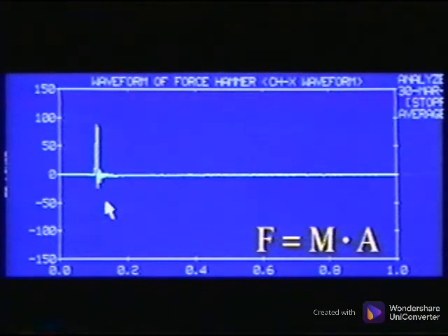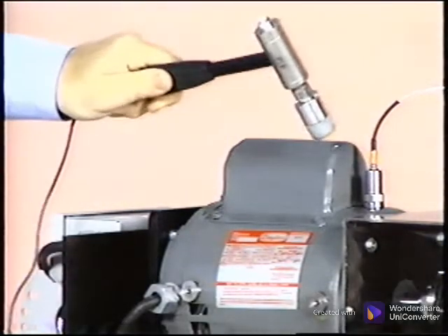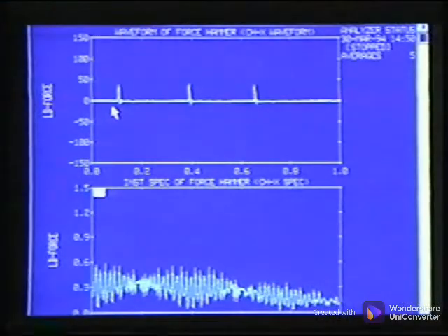Again, the waveform data has the most useful information. In acceleration, these impacts are proportional to the force. When 2 or more impacts occur, the waveform data shows each impact as we would expect. Each of these 3 impacts produces a single non-repeating pulse which imparts all frequencies and creates a continuous spectrum. However, since there are 3 impacts exciting all frequencies, these frequencies will be in and out of phase, adding and subtracting frequencies spaced at the repetition rate of the impacts.